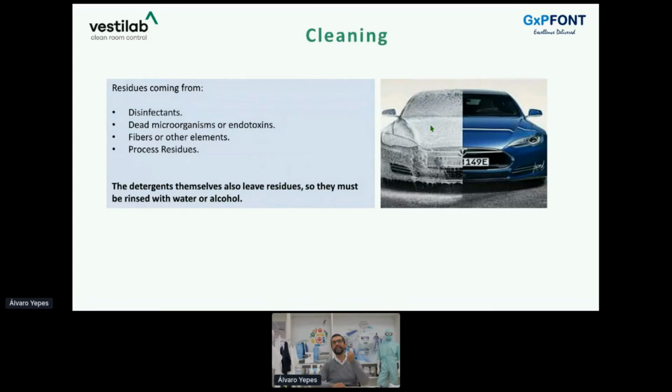So when we're cleaning, it's very critical not only to perform the mechanical action to remove the dirt from the surface, but to guarantee that we are taking it away and removing it before it dries out again. Keep that in mind as compared to a disinfection phase, where most likely you need to achieve a time that is longer than your validated in vitro and coupon contact time. And that probably means leaving the biocides to dry on the surface.